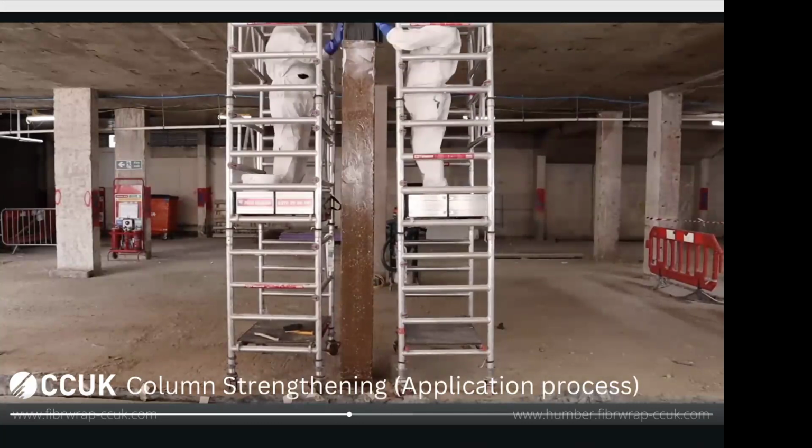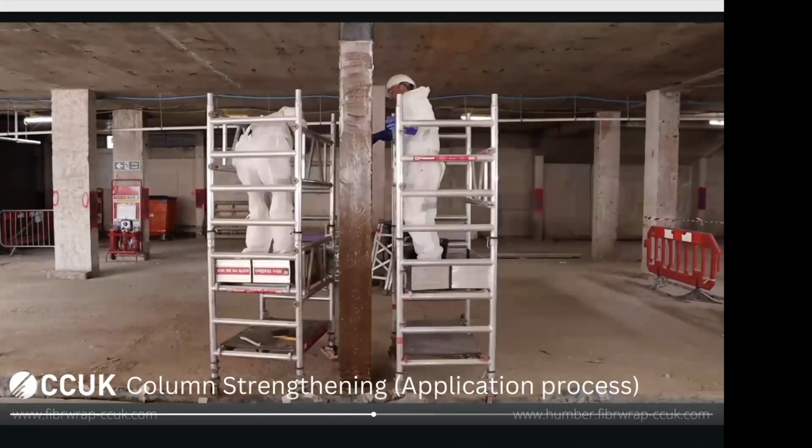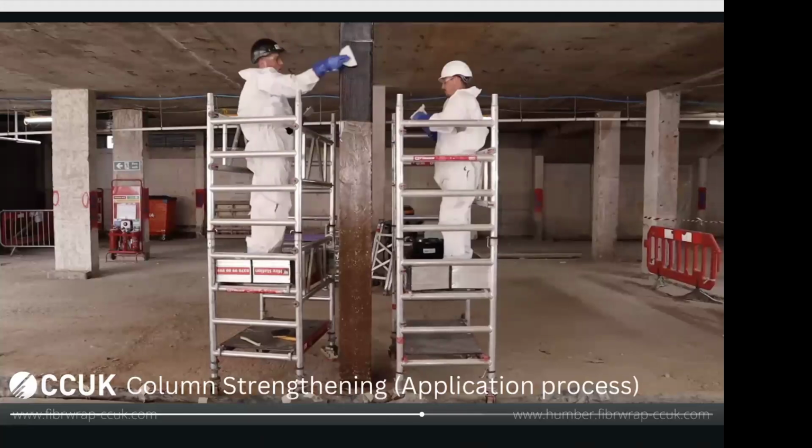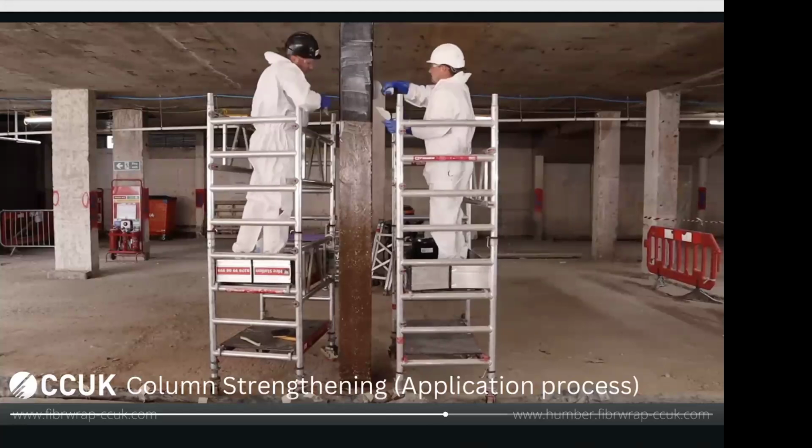Now, because it's a vertical element, you can only apply 3 layers in one day or one shift. After that, you have to come back the next day to apply further layers. But because this was just a 2-layer application, everything was done in one go.